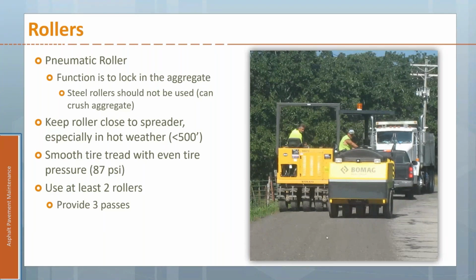We also need the rollers to stay pretty close to the chip spreader, especially when it's hot weather. Remember, we're using a rapid set emulsion, so we need to get in there, get this stuff done, get everything in place, so as it's curing, we're not trying to move particles around. That's going to be even more so in the middle of summertime.